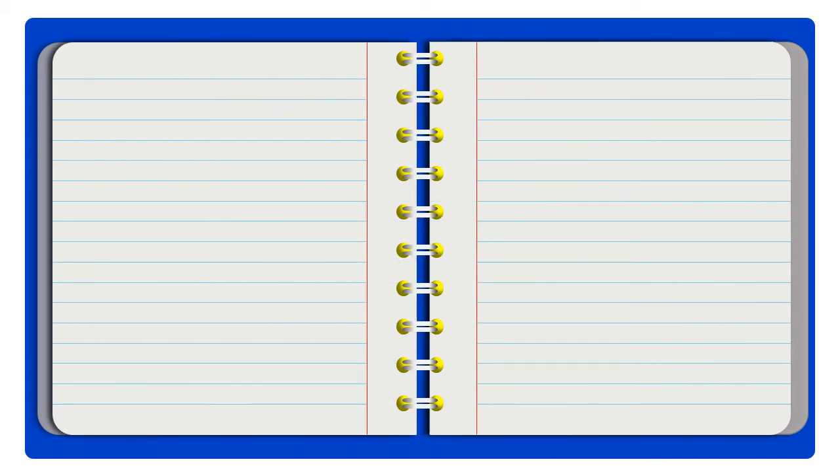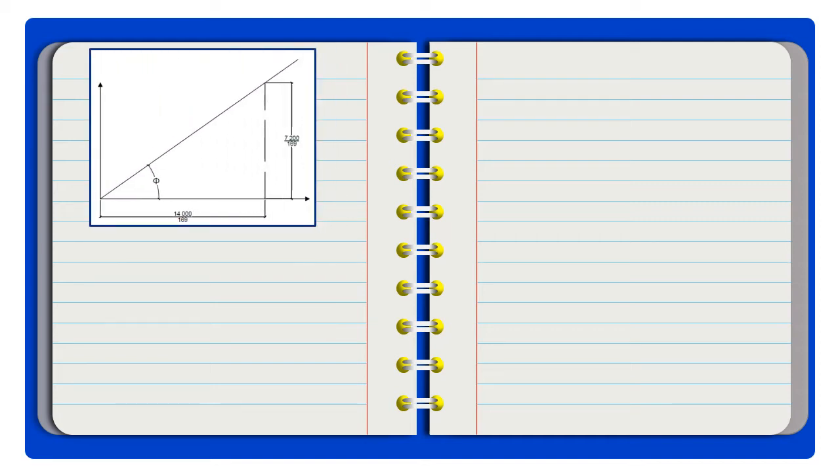So since we have obtained our stresses from our direct shear test, we can now plot them on our coordinate plane. So we plot the normal stress on the horizontal axis, which is 14,000 over 169. Then our shear stress will be plotted on the vertical axis, which is 7,200 over 169. Now, that point is this. So, that is now the location of the stresses we obtained from the direct shear test.